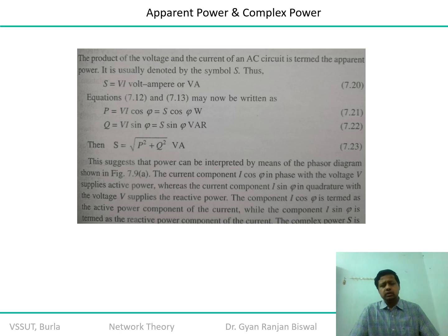You can think about the use of supercapacitors, energy storing devices, fuel cells as storing devices; there are different mechanisms, and things are going on. But the fundamental aspect is that you cannot make the reactive component, VI sin phi, equal to 0. You have to have something, right? It gives you a certain amount of VAR, and that is the amount which you are compromising from the wattage. That wattage plus the reactive power, that is volt ampere reactive, in total gives you volt ampere. Remember this.